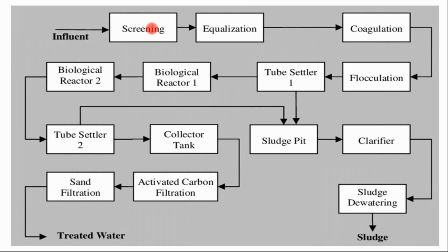So the screening may be a bar facility, that may be a fixed facility, that may be a variable or portable facility, that may be a hydraulic-based bar facility. Depending on the facilities required by your industry, this screening is required. Screening is nothing but the facility to separate out the solid particles, the floating materials, or the large-size particles from this influent. That is simply called screening.